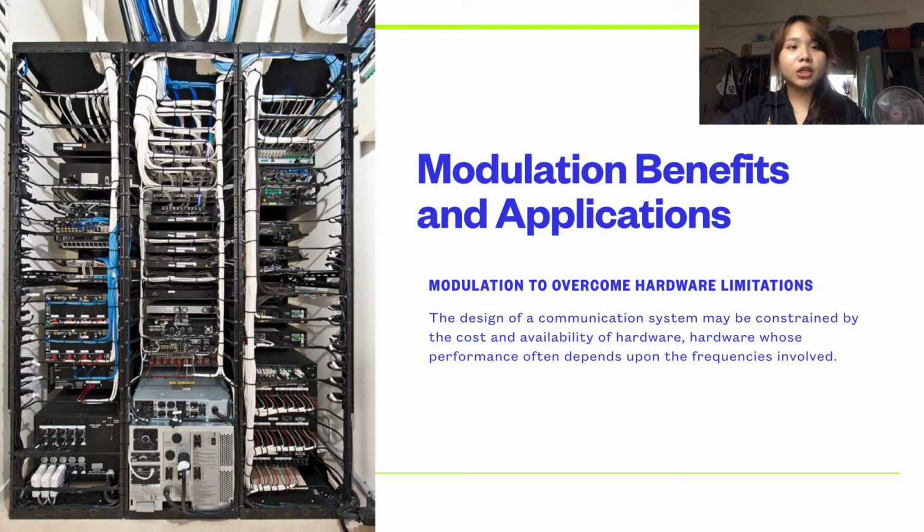A particular concern along this line is the question of fractional bandwidth, defined as absolute bandwidth divided by the center frequency. Hardware costs and complications are minimized if the fractional bandwidth is kept within 1 to 10%. Fractional bandwidth considerations account for the fact that modulation units are found in receivers as well as in transmitters.